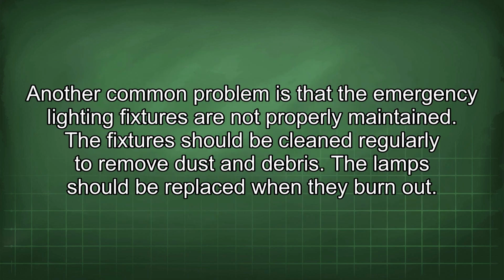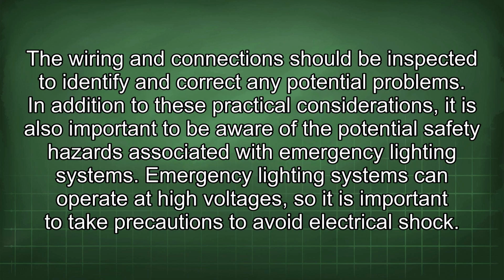Another common problem is that the emergency lighting fixtures are not properly maintained. The fixtures should be cleaned regularly to remove dust and debris. The lamps should be replaced when they burn out. The wiring and connections should be inspected to identify and correct any potential problems.